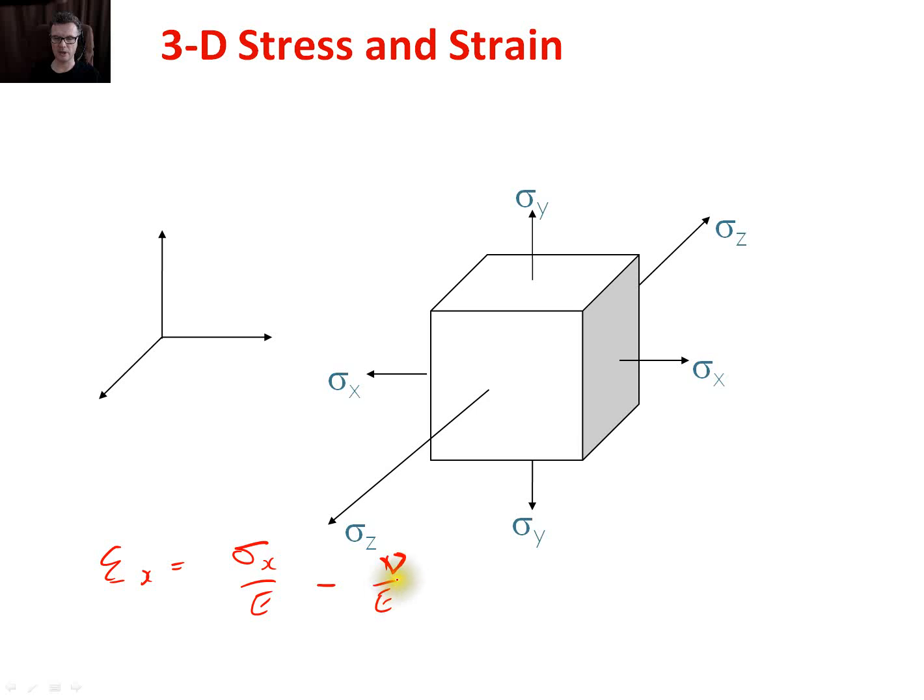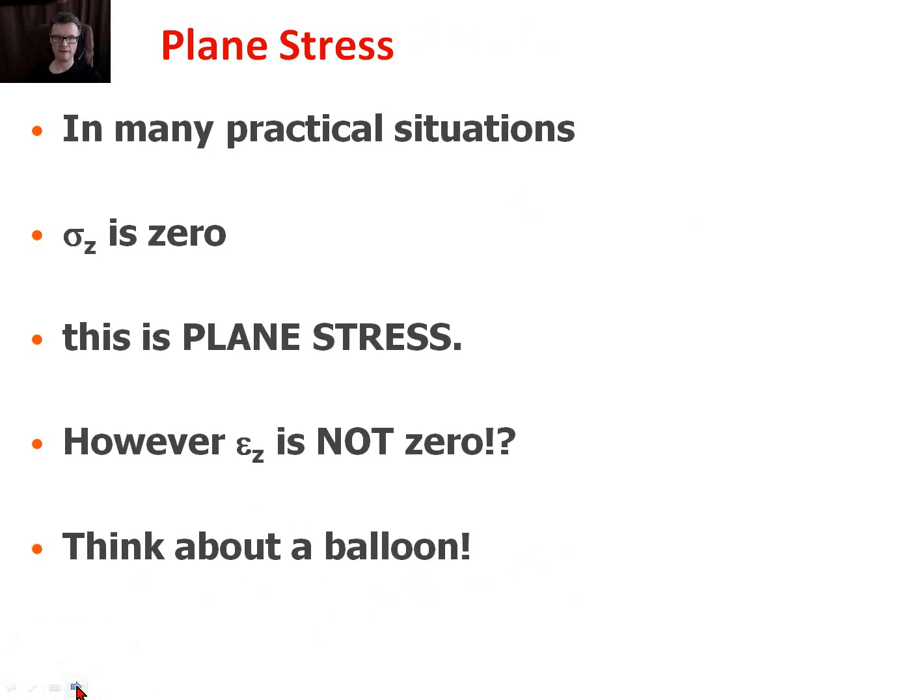Subject to that we're going to get a reduction due to the Poisson's ratio, and we would expect a y there, sorry, and a z. So if I'm now trying to squash it in the y direction and the z direction, then I expect my x direction to be going off, but not as efficiently as if I was trying to pull it in that particular direction. So pulling, if you like, is better than squashing.